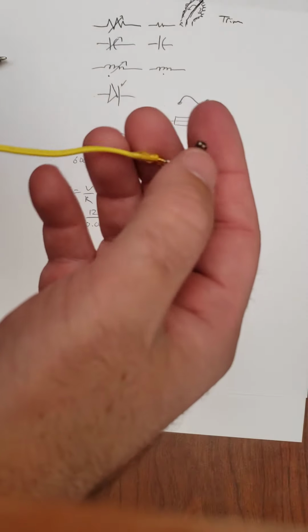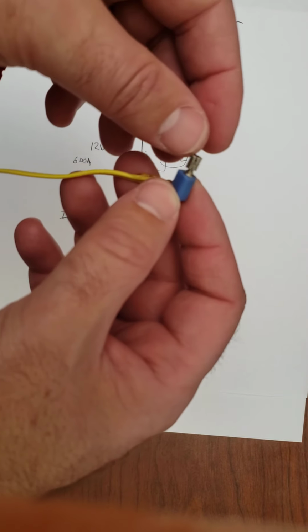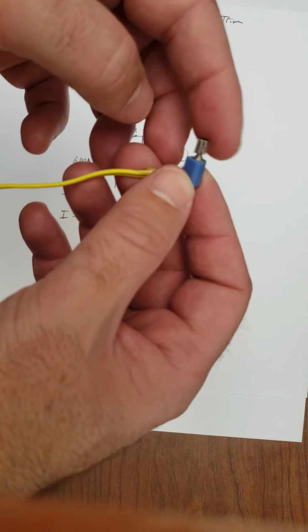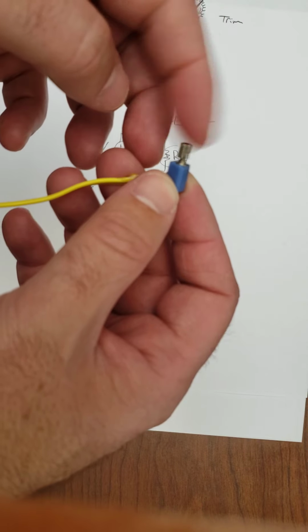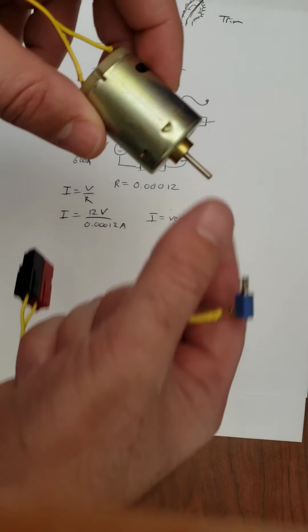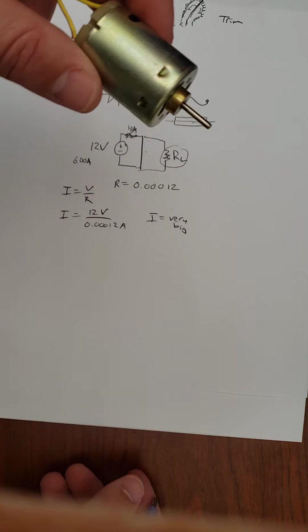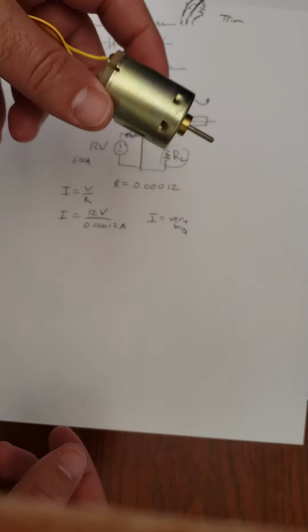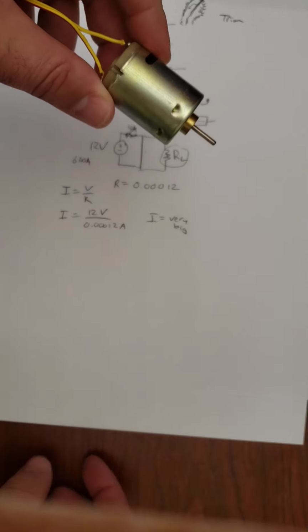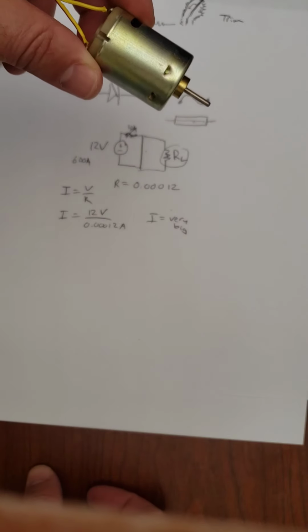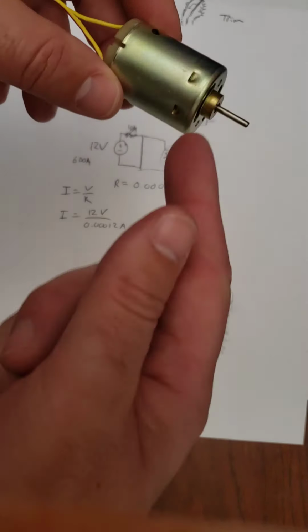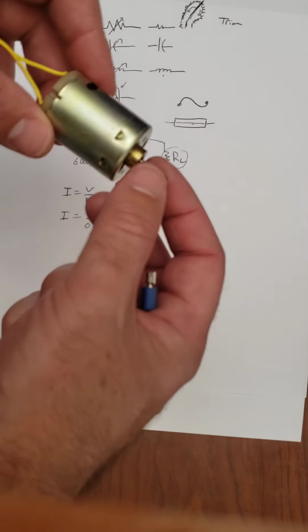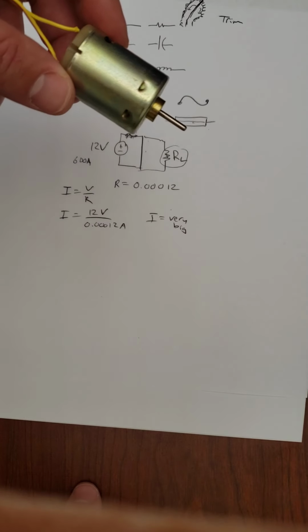If we throw a little weight on the end of it, so I don't know if you can see it, but there's a little tiny motor with a little offset weight. We like motors to spin and not vibrate. The reality is they do a little bit anyway. In fact, one of the things you can do for equipment monitoring is measure the vibration. And when you start to see the vibration getting stronger and stronger, you know that maybe you've got bad bearings, or you've got to clean it, or something like that, so you can maybe fix something before it fails catastrophically.